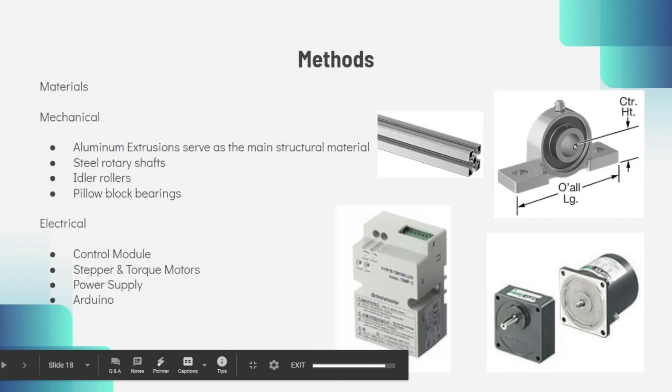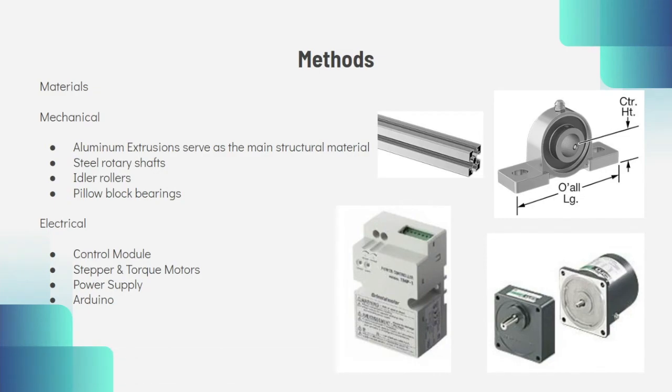For methods and materials, the mechanical portion included a frame constructed using 4-foot-long sections of extruded aluminum. It was important to establish structural integrity, so the choice to use aluminum sections benefits the structure in weight and strength. The aluminum will not oxidize in normal humidity the same way other metals such as iron or low-carbon steel may, thus making it a good choice for corrosion resistance.